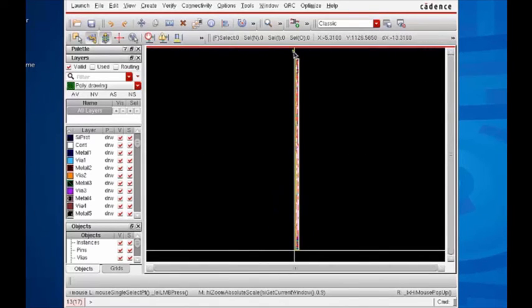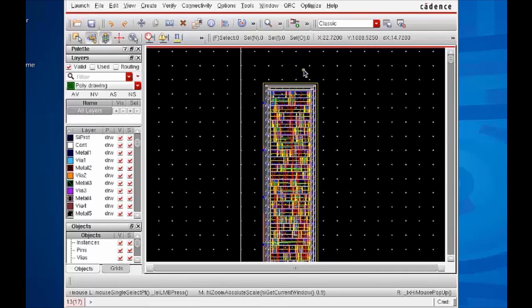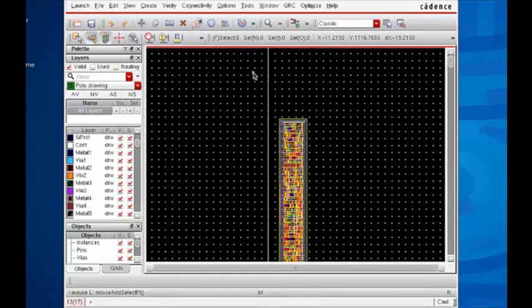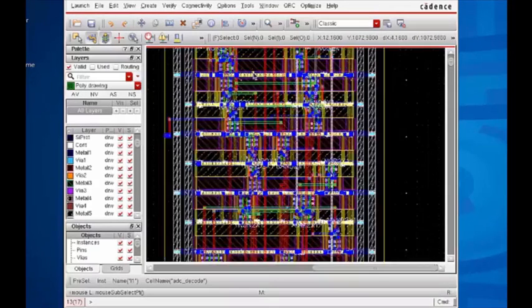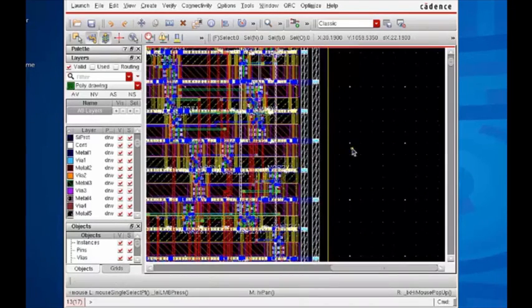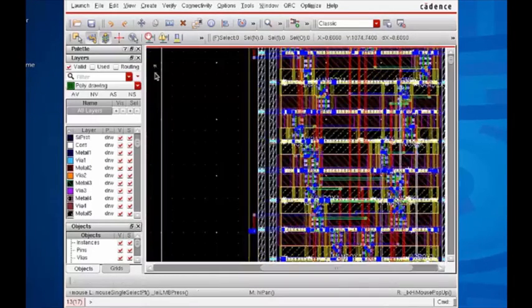and then if we wanted to zoom into it, we get right mouse and drag. And then if we said Shift Z, we're zooming out. If we Control Z, we're zooming in. If we use the Tab key and then hit a new center, we've moved the center of the screen.